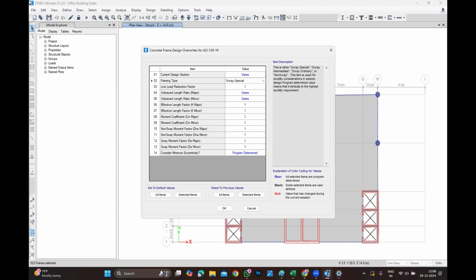If the designer has released this column as a pinned support, you can consider this column as a floating column. If he did not release it, then you will have a fixity. You will have a moment, and then it needs some kind of base to transfer. Then if the beam is even 1 meter, I need to take this column from the bottom of 1 meter. If the slab thickness is 300, I have to take the L bar from 300.